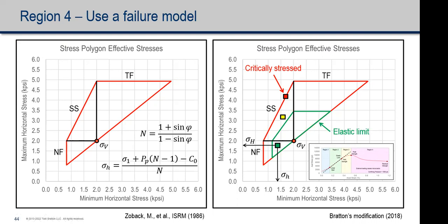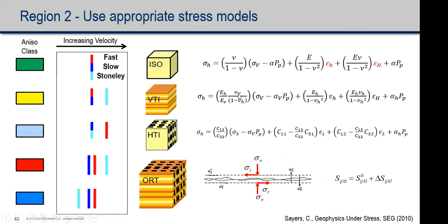You don't have to use Mohr-Coulomb. In fact, you could go to Mogi-Coulomb, you could go to Drucker-Prager, whatever, and get a better estimate of the stress. And I think in many of our critically stressed formations, which are very interesting to us, you look at the literature and you see people still applying this kind of model everywhere, even when I think it's inappropriate. So yeah, dynamic to static, if you're in the elastic domain, then certainly we want the static properties.